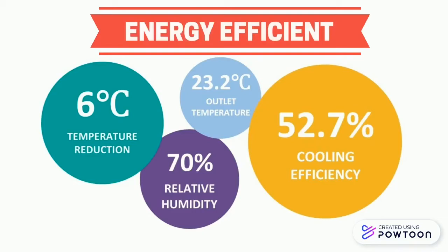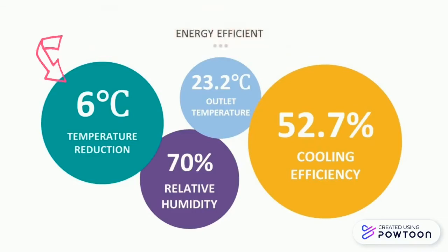Energy efficient. In terms of outlet temperature, evaporative coolers are able to lower the temperature by up to 6 degrees Celsius, which results in 23.2 degrees Celsius of outlet temperature. It is also capable of giving high cooling efficiency, up to 52.7% at a maximum of 70% relative humidity.